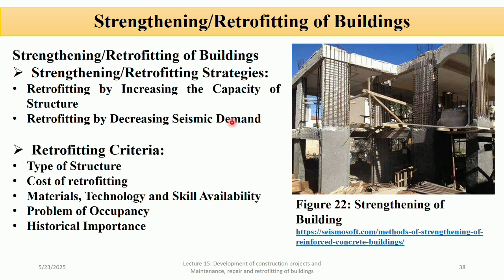And retrofitting by decreasing seismic demands. So this means reducing the amount of force the building has to resist during an earthquake. For example, base isolators, which reduce vibration, adding dampers, which absorb shocks, or making the building more flexible.